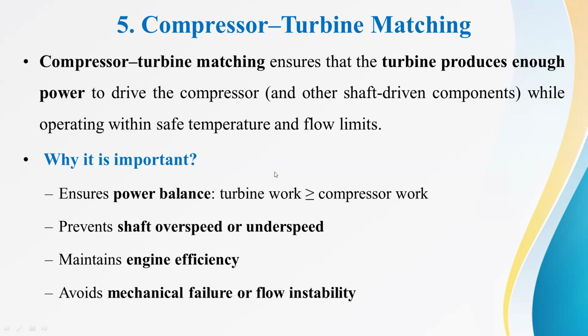The turbine delivers power to the compressor and other shaft-driven components. That is why we are studying this part: to ensure power balance between the turbine and compressor, to prevent shaft overspeed or underspeed, to maintain engine efficiency, and to avoid mechanical failure or flow instability. These are the reasons why we are studying compressor turbine matching.